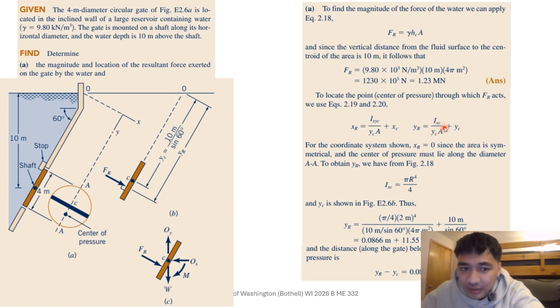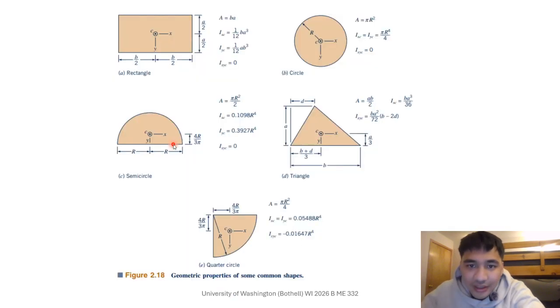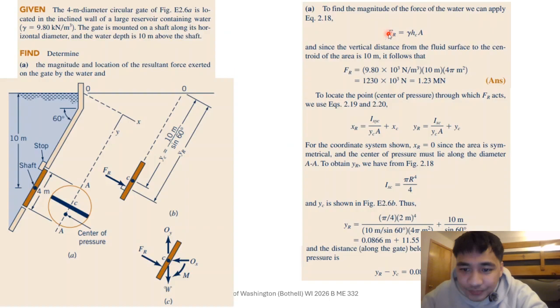So now we're going to find the YR, right? So the area moment of inertia for a circle, lucky us, we don't need to integrate. So we get to skip some Calc 2, which I don't know who's a fan of Calc 2, but that was one of my harder calc classes for me at least. So here we have pi r to the 4th power divided by 4. That's the area moment of inertia.